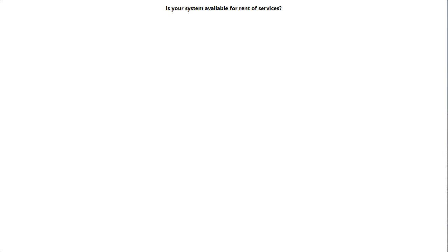Is there a set voxel size for this system, or is it variable? This will depend on your geomag, the magnification that you're at. You're able to adjust the voxel size. We have a 200 micron detector. Our focal spot on the Linac is 0.75 millimeters and 1.5. So we have two different focal spot sizes, but the geomag will affect the voxel size.